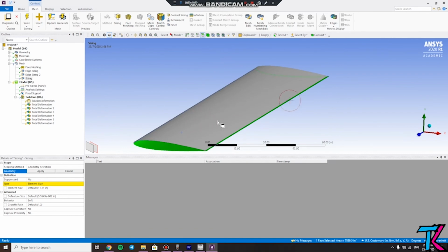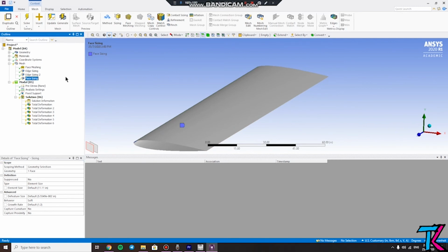So this tool is for you to locate the surface or object or part you want to select, because sometimes the parts are overlapping, and the one you want might not always be at the front. So then you can use this function here to swap the surface to the one you want. Now let's say I want the top surface, then I choose the one at the front. Then I hit apply. Yeah, then okay, now you can see it's here, but I don't want to mess up the file, so I'll just delete it.